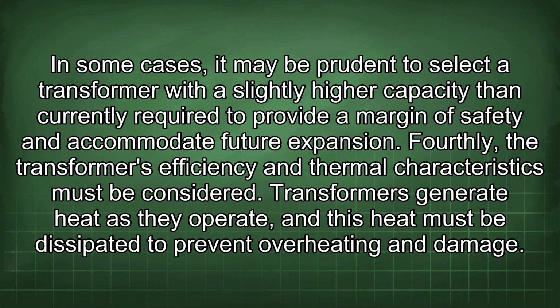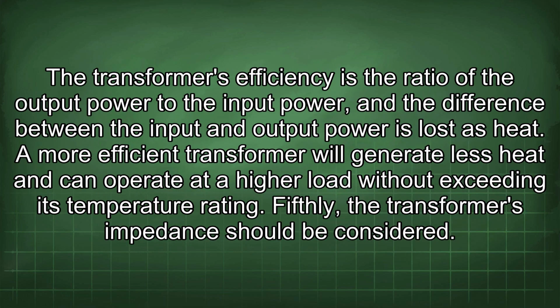Fourthly, the transformer's efficiency and thermal characteristics must be considered. Transformers generate heat as they operate, and this heat must be dissipated to prevent overheating and damage. The transformer's efficiency is the ratio of the output power to the input power, and the difference between the input and output power is lost as heat. A more efficient transformer will generate less heat and can operate at a higher load without exceeding its temperature rating.